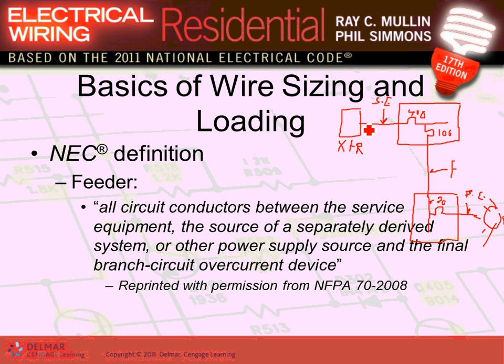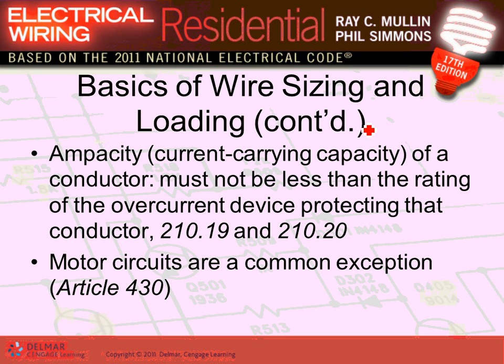Any comments, guys? Any questions? Matthew, does it make sense? So of these three, this one is Article 230, and then Nisi will talk about it. You guys are going to spend the whole year talking with Chad about this. Feeder is Article 215, and branch circuit is Article 210. Any comments, guys, about the difference between service entrance conductor circuit, feeder circuit, and branch circuit? Does it make sense? So that's my circuiting requirement.